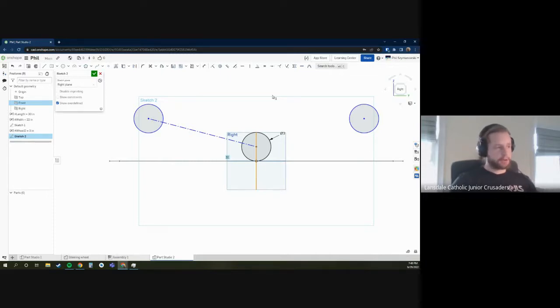All right. Another thing to note is I made this line dotted, and that means construction. The button for construction is right here. It's a solid line and a dotted line with 2 arrows pointing to each other. Construction geometry, construction sketches, and construction points and curves don't allow you to use them for generating solid features like when you extrude or when you revolve. They only give you the line between the 2 points, the curve, just as a reference.